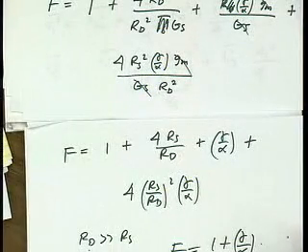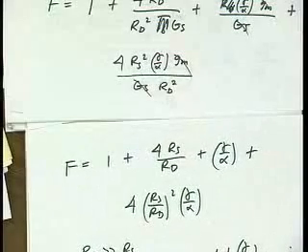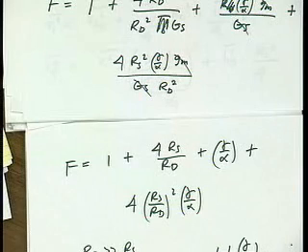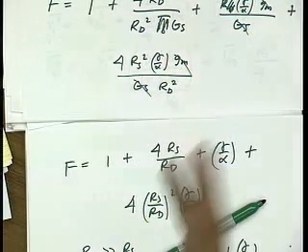Okay, we have another 10 minutes. Let's finish up the last problem. Any other questions about noise? Yes. So for any general cascading, do we multiply the output voltage noise of the first stage by the voltage gain of the second stage and then just add the noise of the second stage? You could do it that way, yeah. You have to be a little careful though. It's a voltage gain squared. You have to make sure that the voltage gain is the appropriate thing to use. In this case, the input impedance is very high, right? So there's no loading effects, so you can just use the voltage gain. If there's some loading effects, you have to take that into account.